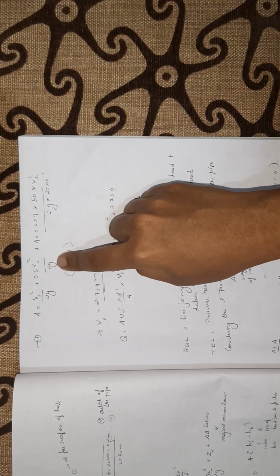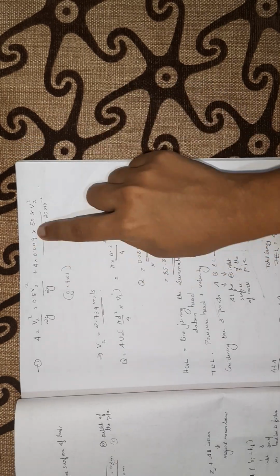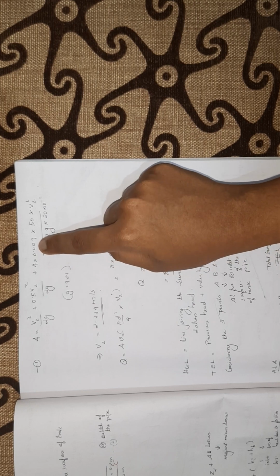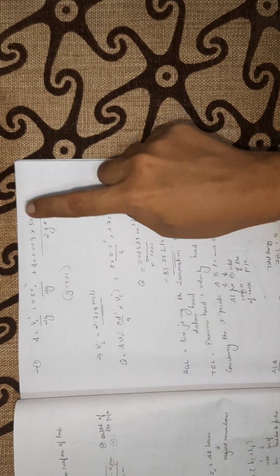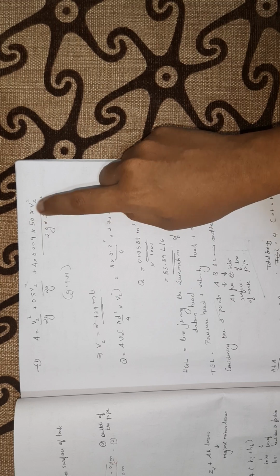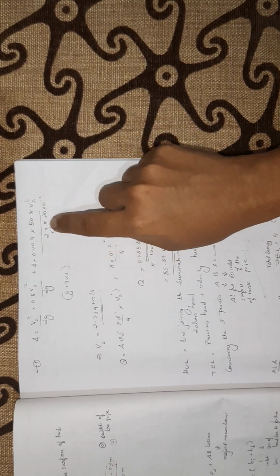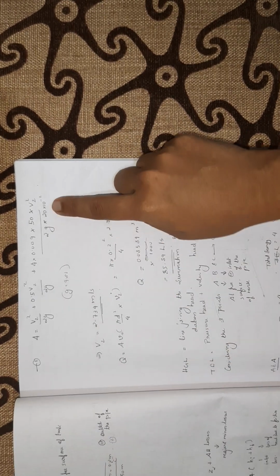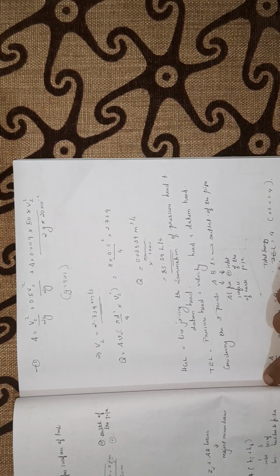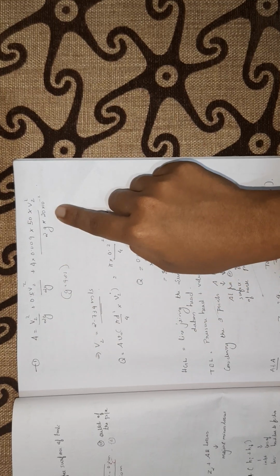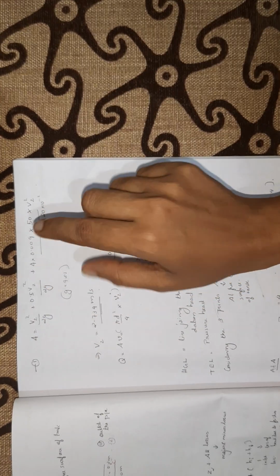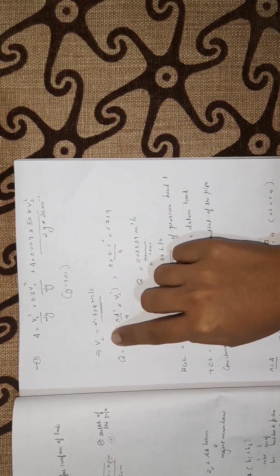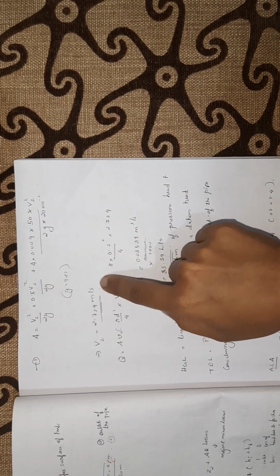This is our minor loss at that inlet. And the friction term 4FL V square by 2GD, that is 4 into F, which was given in the question as 0.009, and length is the length of the pipe, 50 meters, and V2 square by 2G into D, right? 2GD. D is the diameter of the pipe in meters. Okay, so after solving this equation, since every term is in terms of V2, we can solve for V2. So we got V2 as 2.734 meter per second.